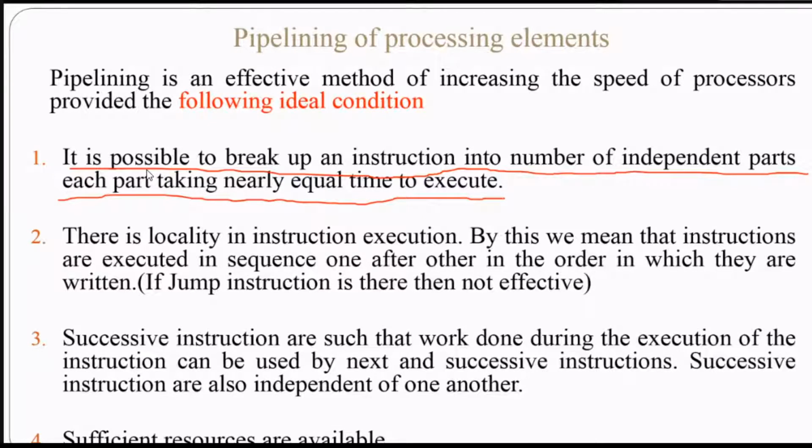So the instruction जो हम execute करेंगे, हमारा program execute करेंगे, उसमें जो एक instruction execute करेंगे, we will divide it into these 4 stages. This is just one example that you can divide it into 4 stages. And these 4 stages should take equal time. आपका जो instruction fetch करने का time है, instruction decode करने का time है, instruction execution का time है, वो same होना चाहिए. So that is a false assumption.